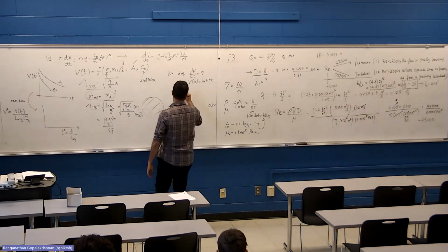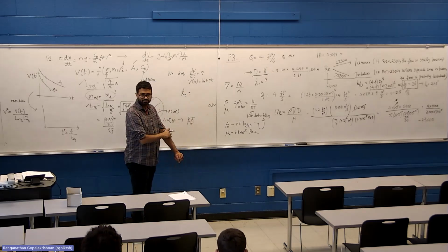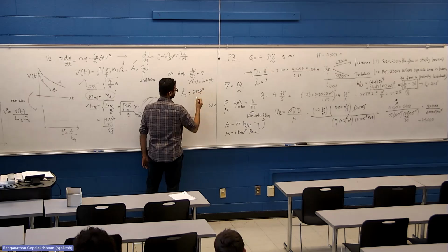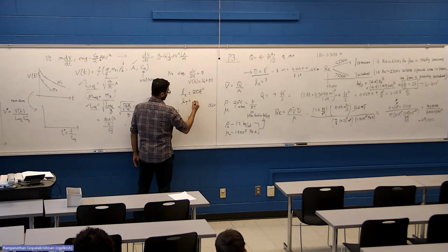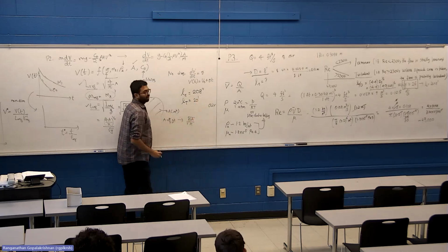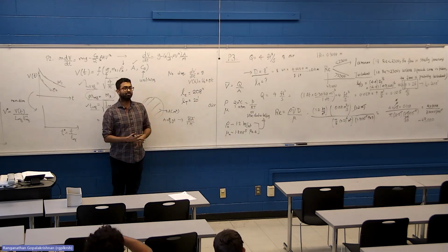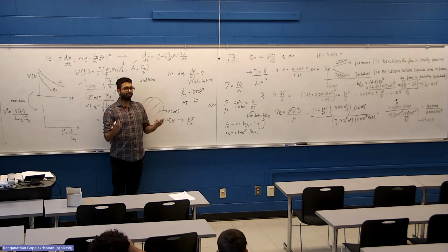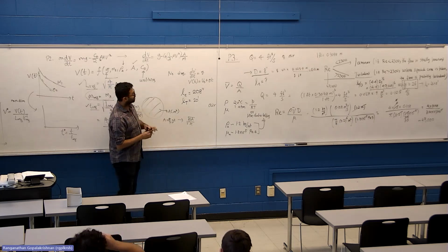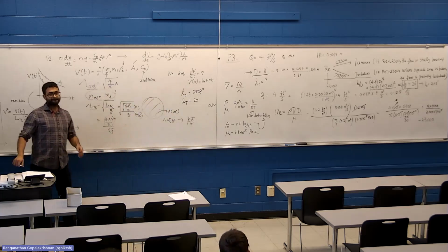If LE happens to be 208 inches, and the total length of the pipe happens to be 20 feet, is it reasonable to neglect the entrance length portion in your flow rate calculation or pressure drop analysis? Yes or no?